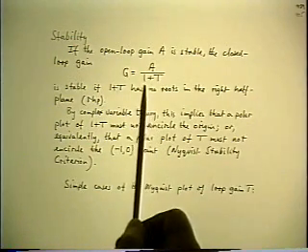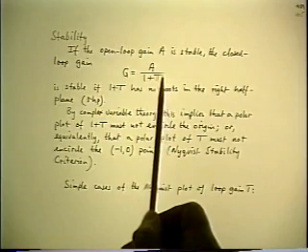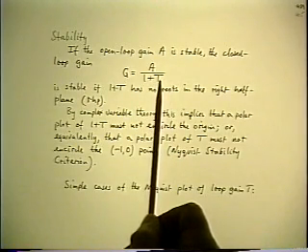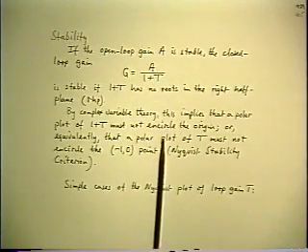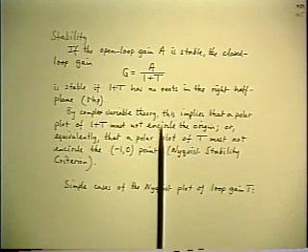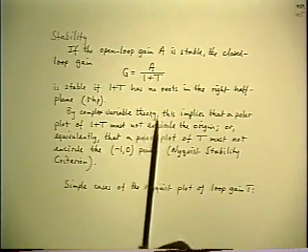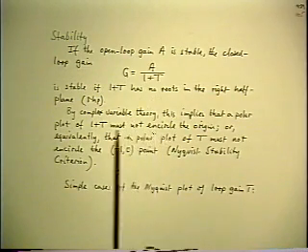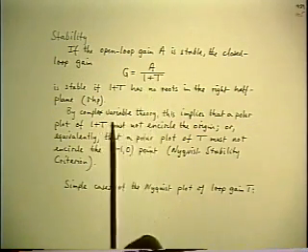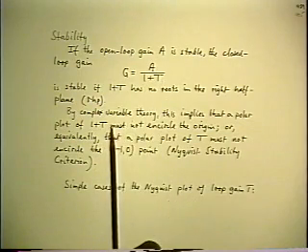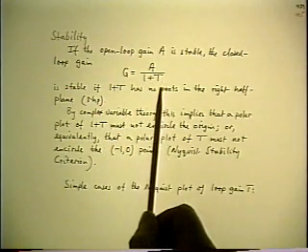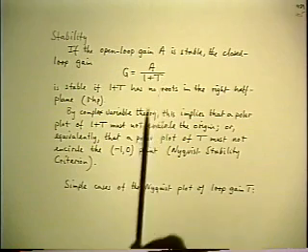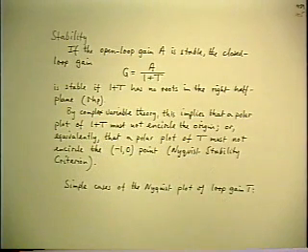Because F is actually a derived quantity, T is really the fundamental quantity, usually that result is also translated to say if the contour of F does not encircle the origin, since F is simply 1 plus T, there's a unit shift. And the equivalent condition is that the polar plot of T should not encircle the -1 point. That's obviously the same thing, just shifting the effective origin by 1 unit.